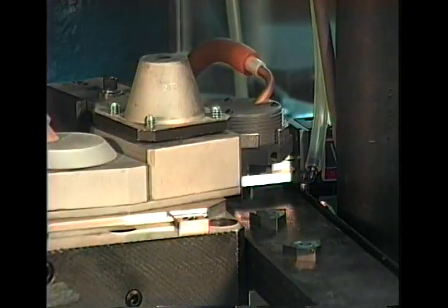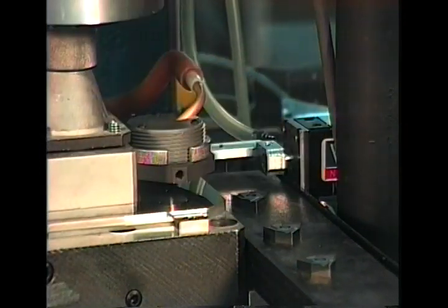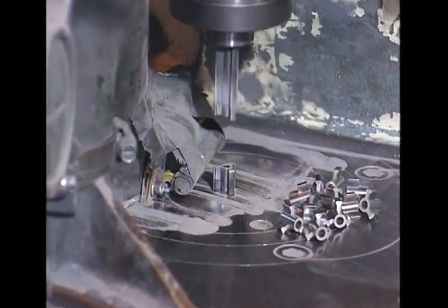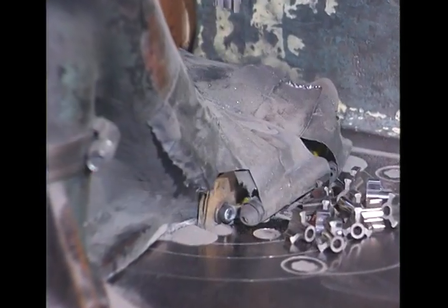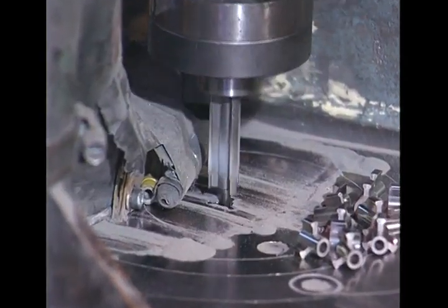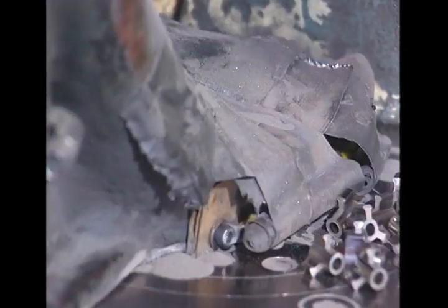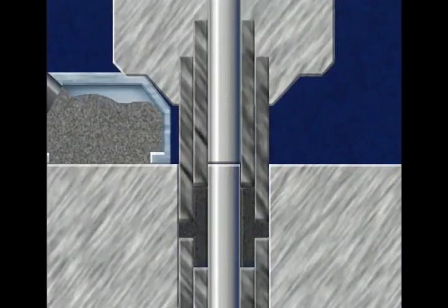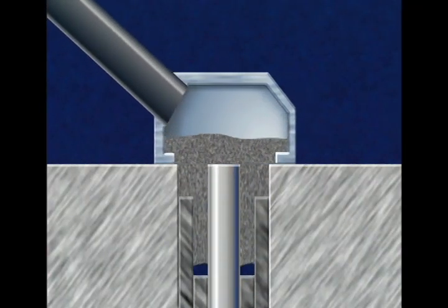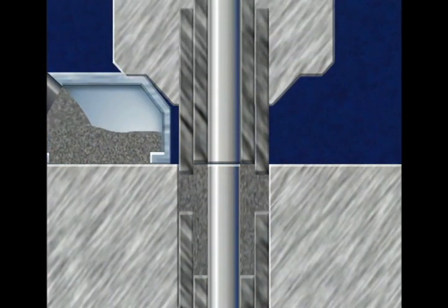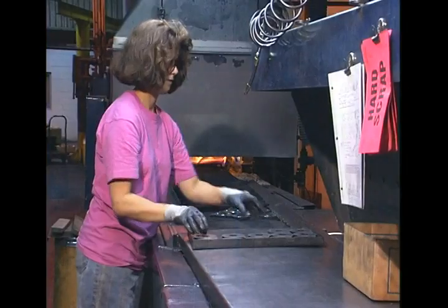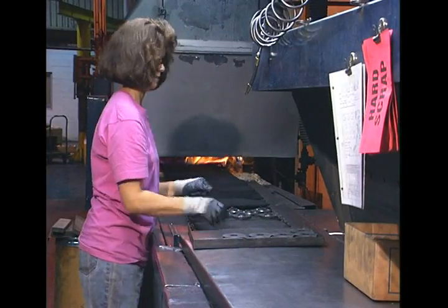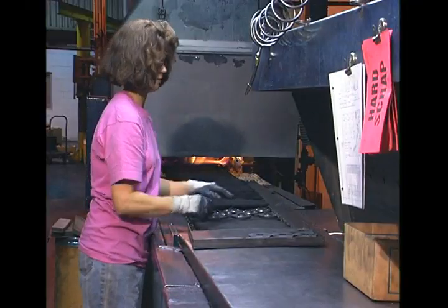Ejection from the press can also be accomplished using automated handling equipment. The density of pressed powder tends to decrease along part height as the distance between the compacting punch and die increases. To produce more uniform density, thick parts are compacted by a set of upper and lower punches. After pressing, parts are transferred to the sintering furnace.